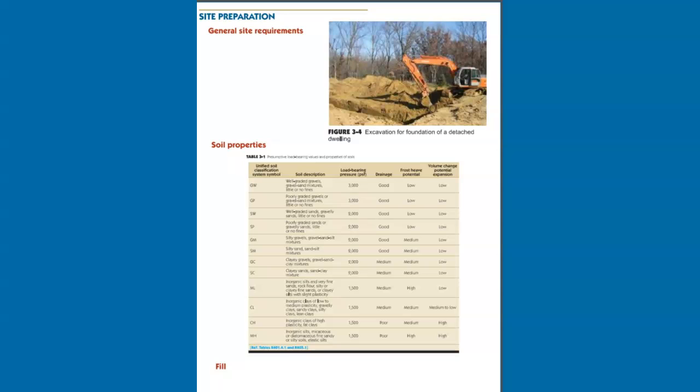Over-excavation to remove unsuitable soils or the addition of material to raise the elevation of the footings above the level of the natural undisturbed soil requires engineered fill material to support the footings and foundation. A registered design professional is responsible for the design and placement of the fill material in accordance with accepted engineering practice. The engineered fill must be installed and tested in conformance with the design requirements.